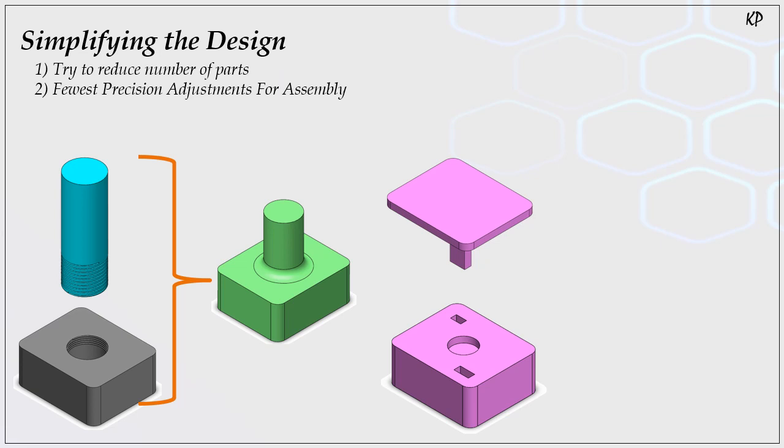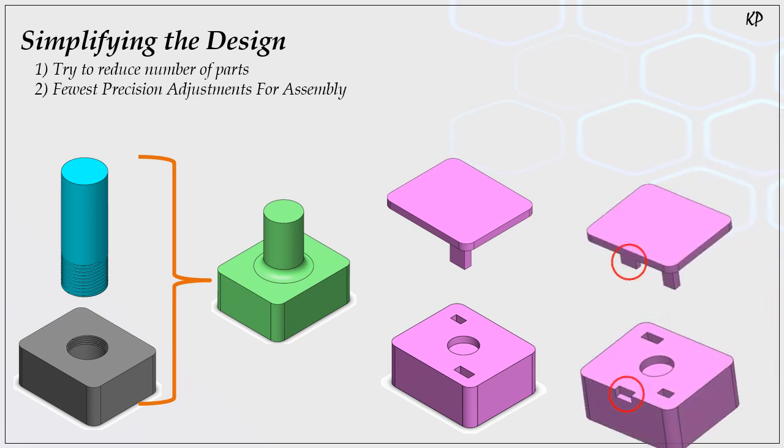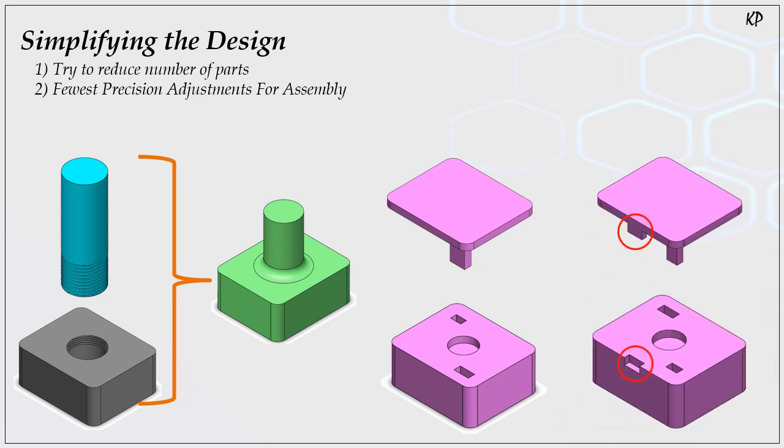So while assembling, anyone can match that protrusion on any socket hole. It might not be correct functionally, but the assembly person does not know that. So he can assemble in any direction. So to avoid this mistake, we can add a simple notch on one part and a protrusion on the other part, as seen in the second image with the red mark.